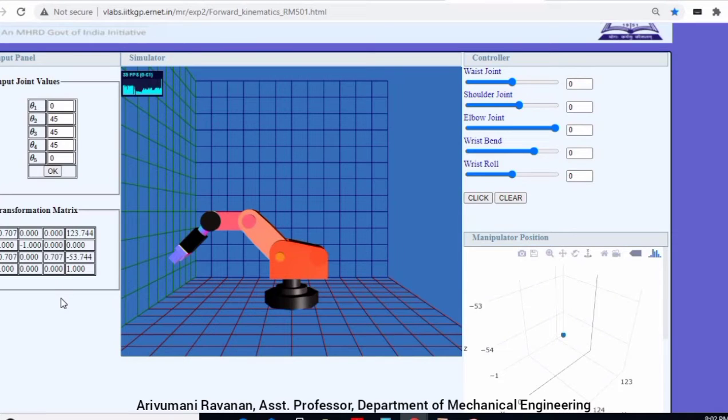Generally, the RM-501 drive unit provides the intelligence and control for the robot unit. The drive unit computes all the arm control information for each instruction. It handles arm velocity, acceleration, deceleration, and movement trajectories for the user. The drive unit is interfaced to the host computer processor through a controller interface.